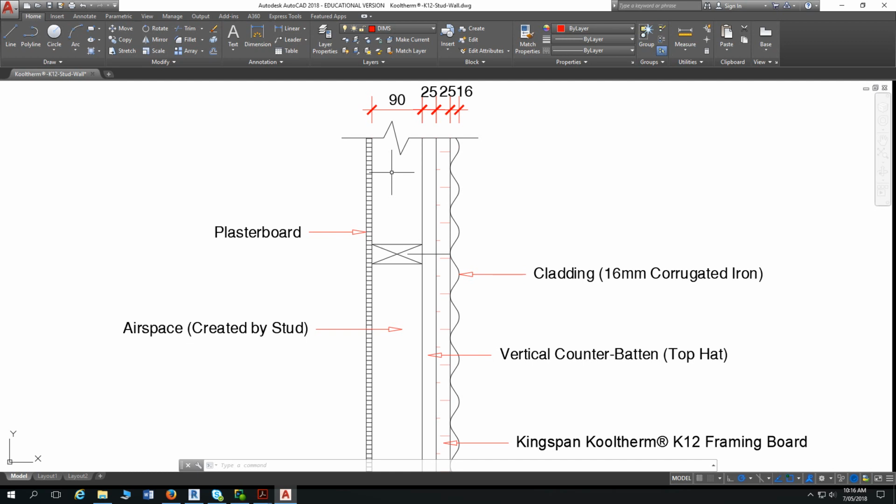So this wall type starts off with a 90mm stud wall. On the inside we have plasterboard. And how thick is plasterboard generally? 15 or 10mm actually. 10mm. Yeah. Generally 10. Okay. So the common name for plasterboard? Gyprock. Okay, the Americans call it drywall. You've ever watched an American show? Yeah. So that's on the inside.